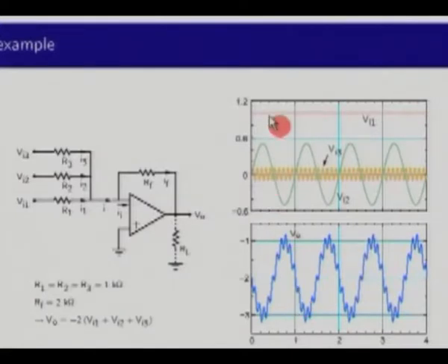And you see that this DC voltage of 1 volt has given you a shift of minus 2 volts at the output, and it's also a good way to point out that op amps work for DC input voltages as well as AC input voltages, which a common emitter amplifier cannot do.